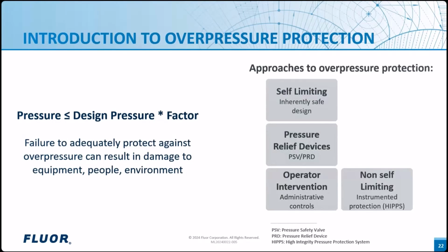Typical credible scenarios are described in the American Petroleum Institute's API 521 and include, for example, pool fires and maloperation of valves. This assessment of credible upsets is a key activity in the design phase of a project. Each plant will typically have some unique aspect that requires an assessment of the system as a whole to understand how the systems interact and respond during the upset.